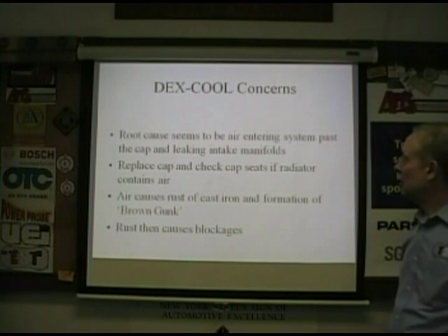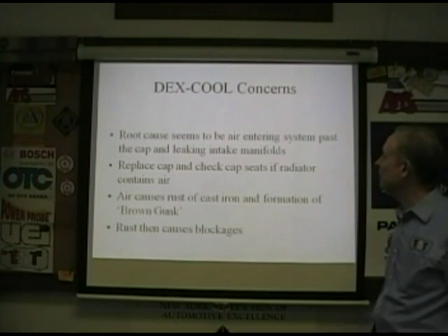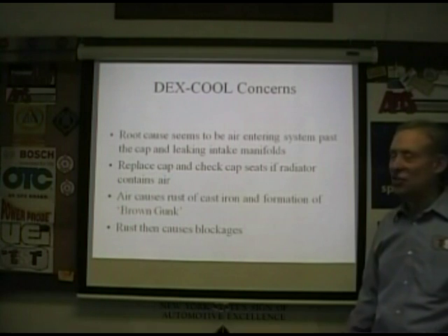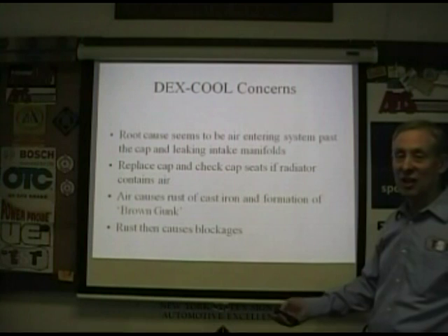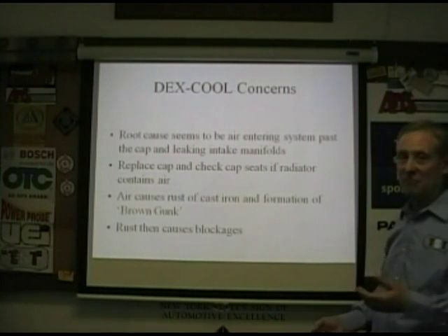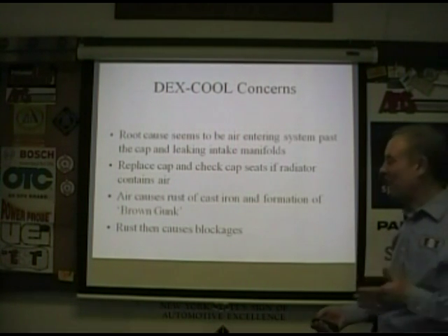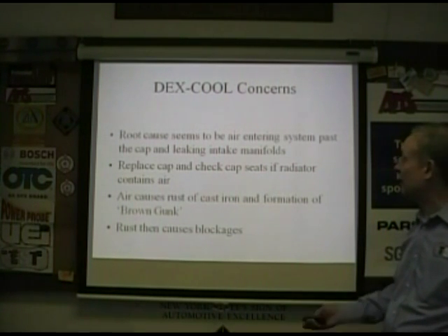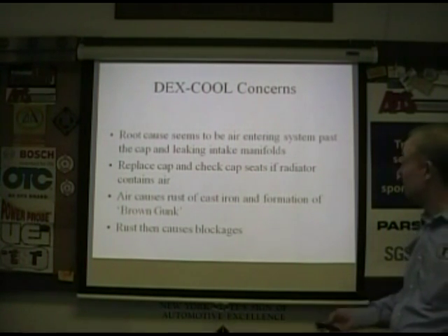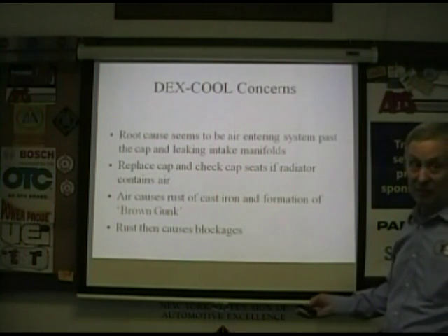Dexcool concerns that are kind of unique to OAT technology. Root cause seems to be air entering the system. You get aeration. You end up with a little chemistry change, and you end up with the brown gunk. This is not the jello effect. This is that mud effect. I'm not sure mud's a chemical term, but it looks like mud. And it blocks things up, causes local hot spots, overheating, and it's a real bear to get it out. Yeah, I've seen that a lot on GM cars. Yeah. We've seen it at Volkswagen to some degree.